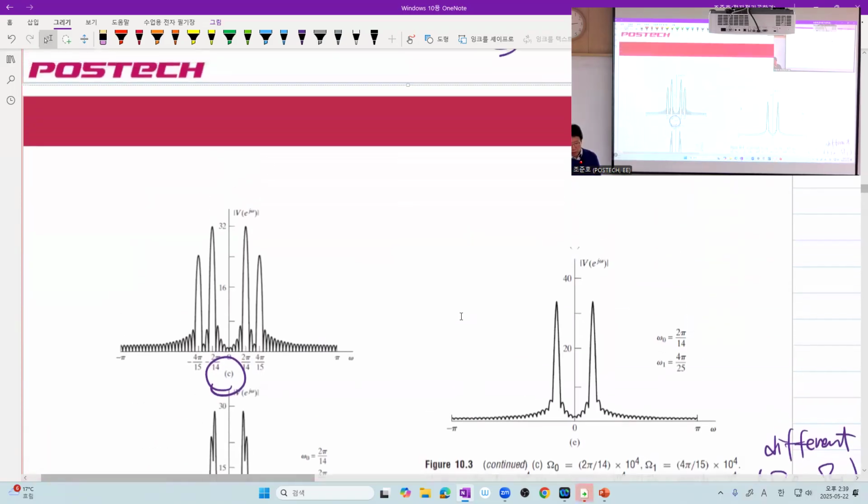And now, here goes a more challenging case. Now, they are very, very close. And what happens here? Most of you would say, without knowing two signals existed, that maybe it is just one signal with some possibly corrupting interference or noise. Ready? So we have a dilemma. We want to have a smaller width of the main lobe, but we also want to have lower side lobes. And that cannot be satisfied at the same time.